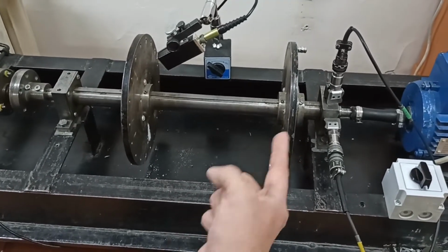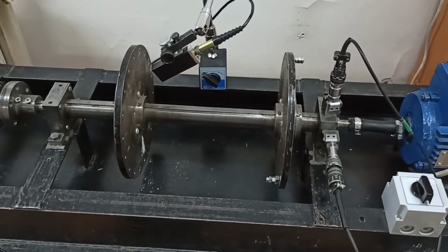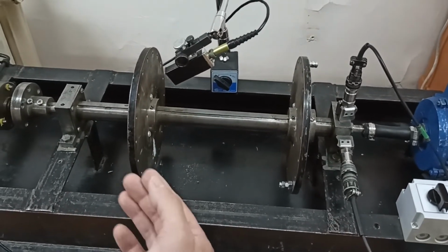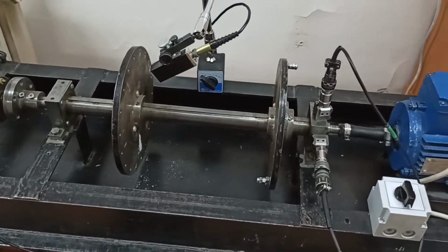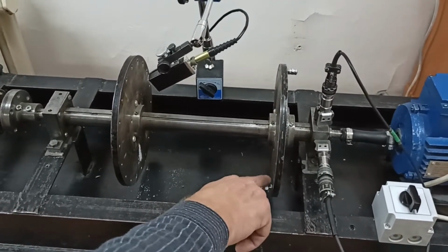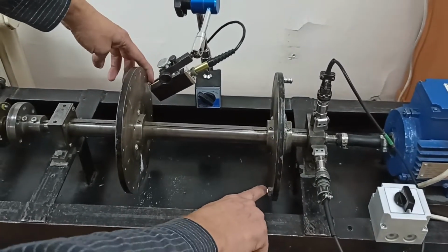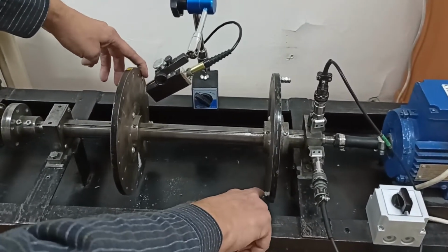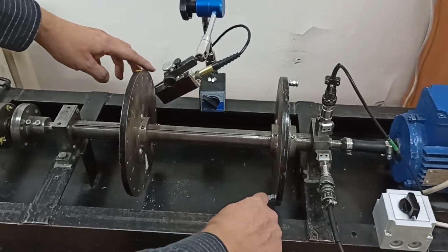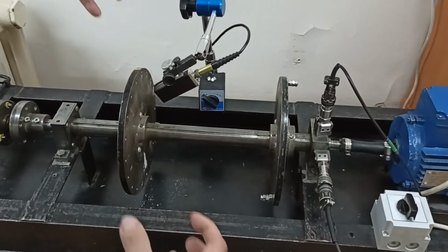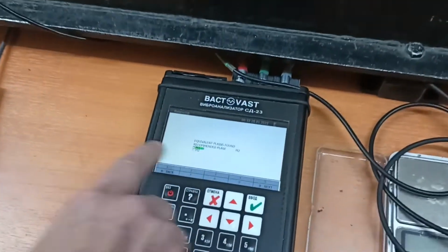We can select only one plane, either of them, and fix only one weight, and in this case the machine will be balanced. In the opposite situation, you can, for example, install a big mass here and a big mass on the opposite side of the machine. Actual influence will be on the difference between these two masses, but the big amount of masses can tear the rotor. So it is actually recommended to select only one plane.